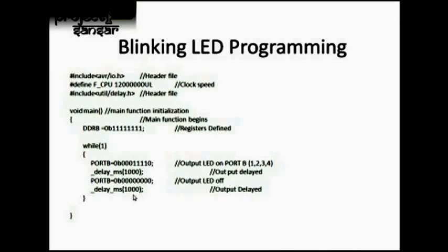So your LEDs go off. Once again we want it to be in that position for 1 second, so again we put it as _delay_1000. The program would start reading from here. It would see, okay, the user wants port B as an output.